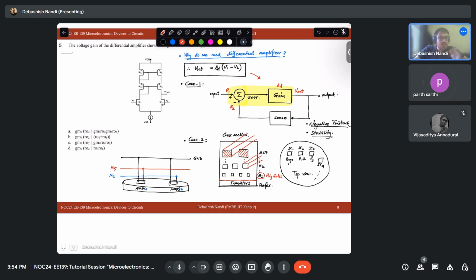So how to compensate that? Thicken your wire. R is equal to rho L by A. Your L is increasing as your metal levels are getting higher, so you need to increase the area, or make the wires fatter.